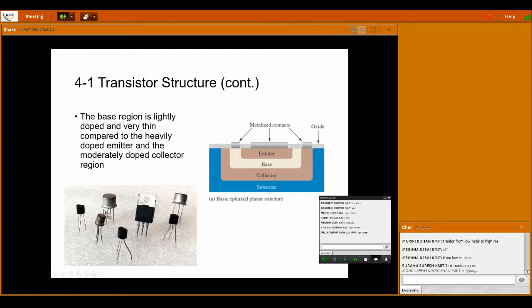Here, just look over there. There is an extra part, which is known as a notch. If we have a transistor of cylindrical shape with an extra part called a notch, from that notch we have to move in an anti-clockwise direction. The terminal nearest to the notch is the emitter, then the base, and thereafter the collector.